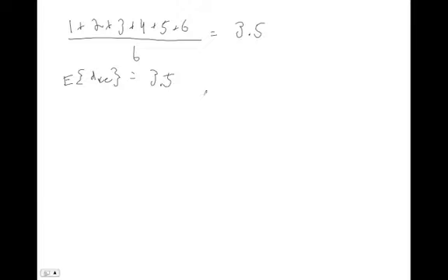Okay, so we've said that this disturbance value on average is captured by the matrix V. We've seen that the noise value on average is captured by the matrix W. We have to say that V and W are both positive definite matrices, and that's just going to come out of the fact that you're taking numbers and timesing by themselves. So every element in V is essentially a disturbance value times itself. Whether that disturbance value is positive or negative doesn't matter, because when you square it, it's positive. So these are going to come out to be positive definite matrices.